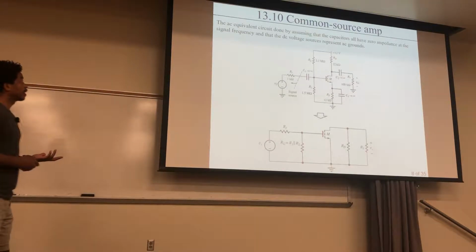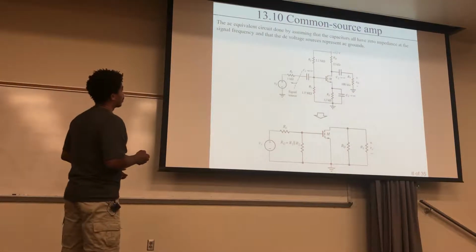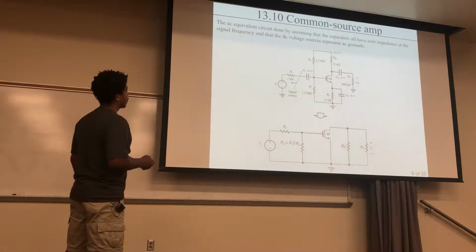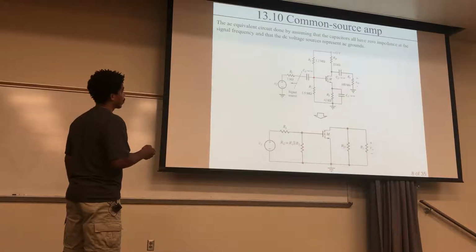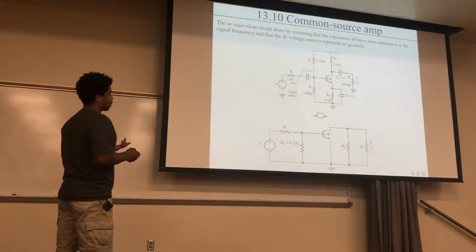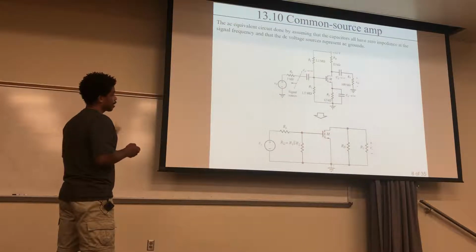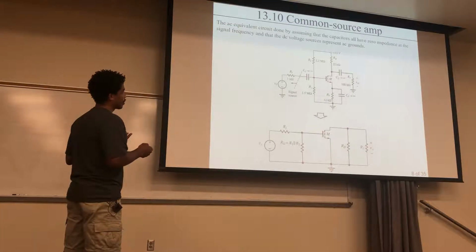First thing you do is your AC analysis. These capacitors become DC current blockers, and this one becomes an AC current bypass.